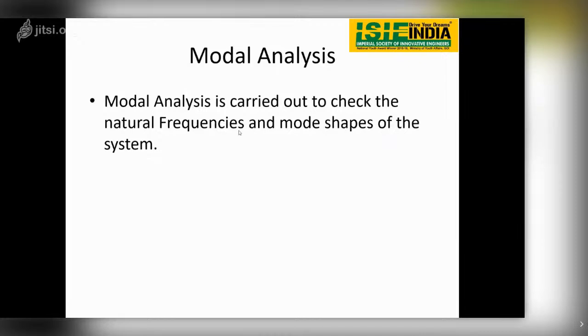The natural frequency of the system is calculated just to know the resonance effect, because if the natural frequency of the system matches the natural frequency of a surrounding component, it will lead to maximum vibration. The phenomenon is called resonance, and it results in the failure of the component.